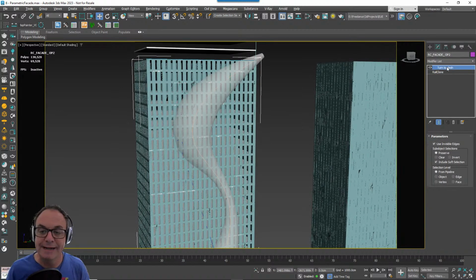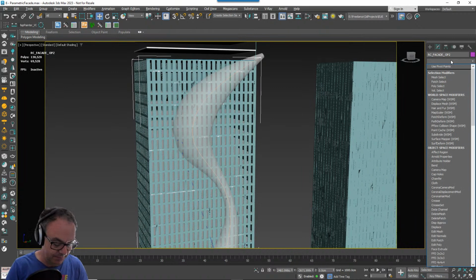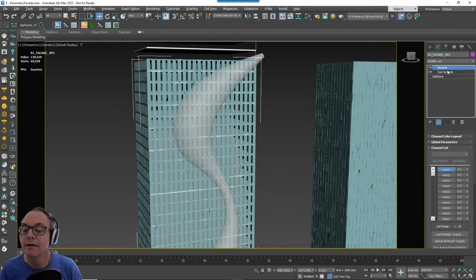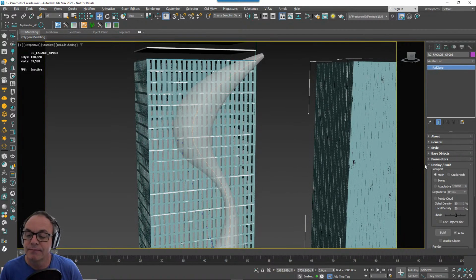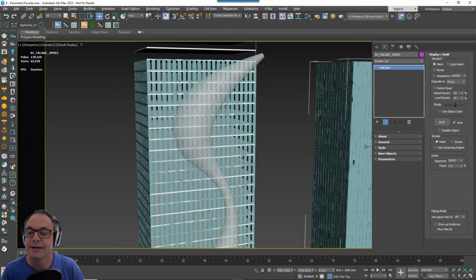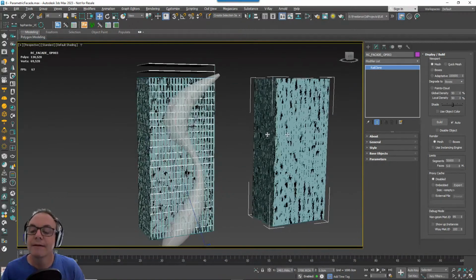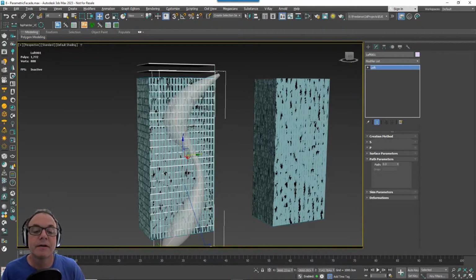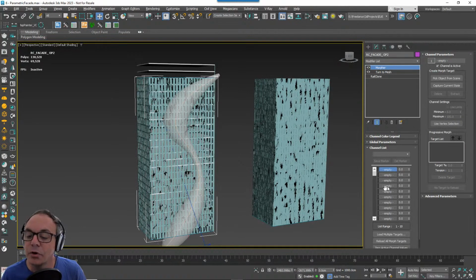So now we're into standard Max stuff for a little bit. So I'd come into here and add a Morpher modifier. Let me just unfurl that a little bit. Come on, behave yourself. There we go. Just want to open that up. Right. And then in the Morpher modifier, you can see I've got my morph states down here, and I've got the amount I'm morphing between them here. To create a morph target, I want to click pick object from the scene and pick it from here.